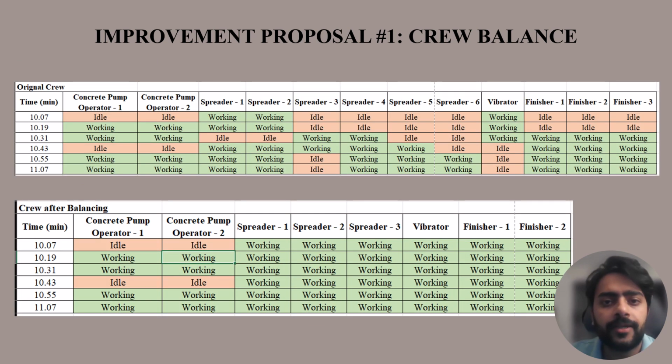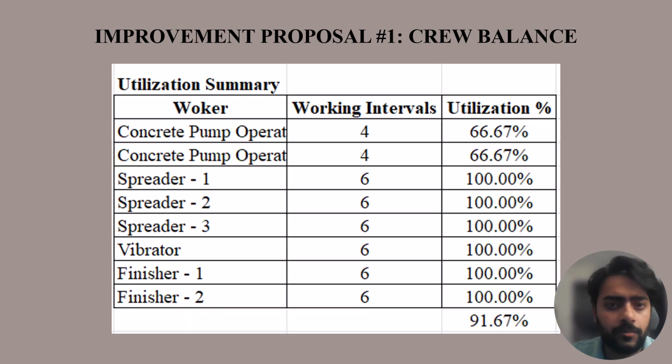This side by side timeline clearly shows the difference. Before, many crew members had long idle periods, especially among the spreaders and vibrator operators. After balancing, everyone was actively working across all intervals, and this simple adjustment helped create a smoother, more synchronized workflow.